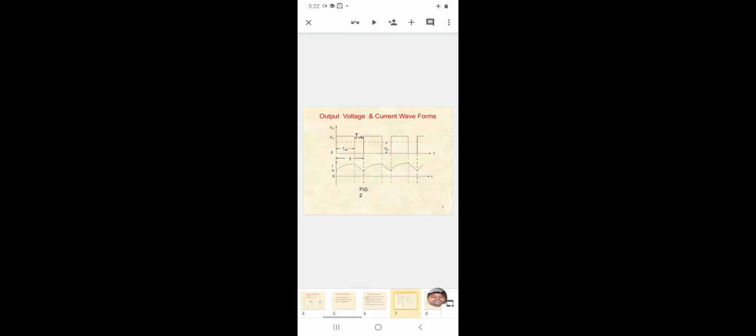Here the freewheeling diode starts conducting and forms a closed loop. The output current flows through the inductance, load, and freewheeling diode. So the current goes from maximum to minimum. The energy stored depends upon the value of inductance, and it discharges completely, from maximum to minimum.